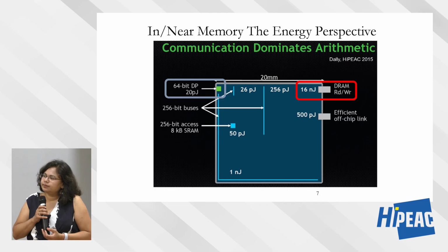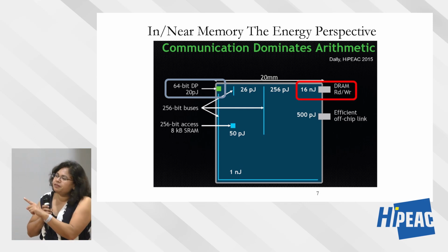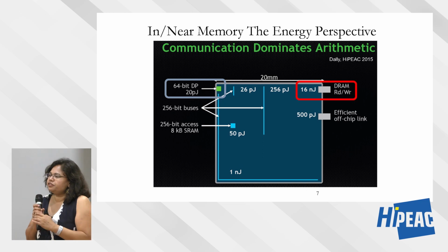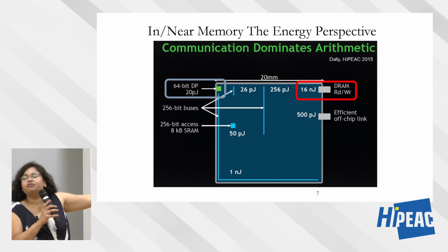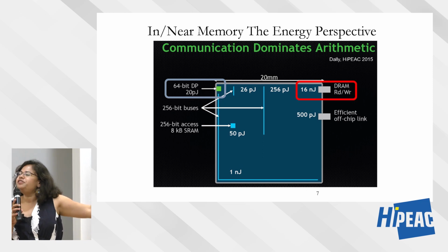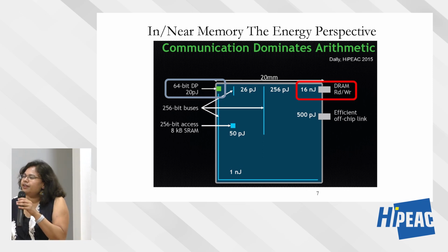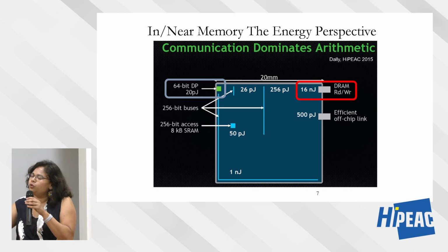You have to go through all the interconnects and then go to the cache. Yeah, the cache is always very big. Big means that it has a lot of energy consumption, especially for static energy consumption. Right, but you would be surprised, and I'll show you in the next lecture. They are big, but most of that energy is coming from the interconnection. Yeah, the actual SRAM access is very small, 50 picojoules. All of it is coming through that little ring, bus, and all that, which goes to that SRAM array.